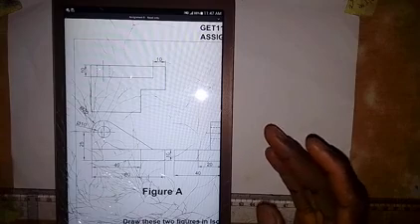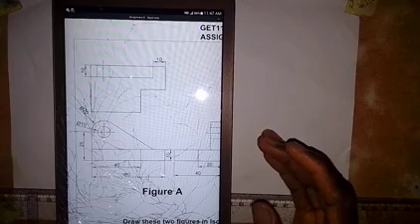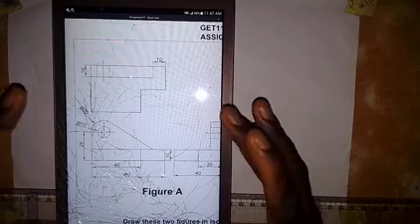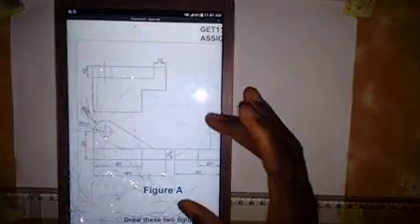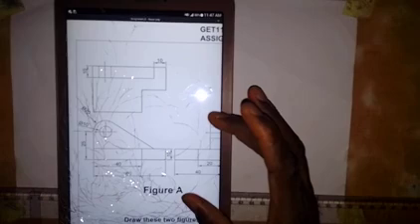And some other parts that will be laid on the receding side of the block, we have to divide them by 2, and that's going to be very small. Okay, so I will leave the dimensions as they are and produce the oblique projection of this in the Cavalier method, or Cavalier oblique projection.